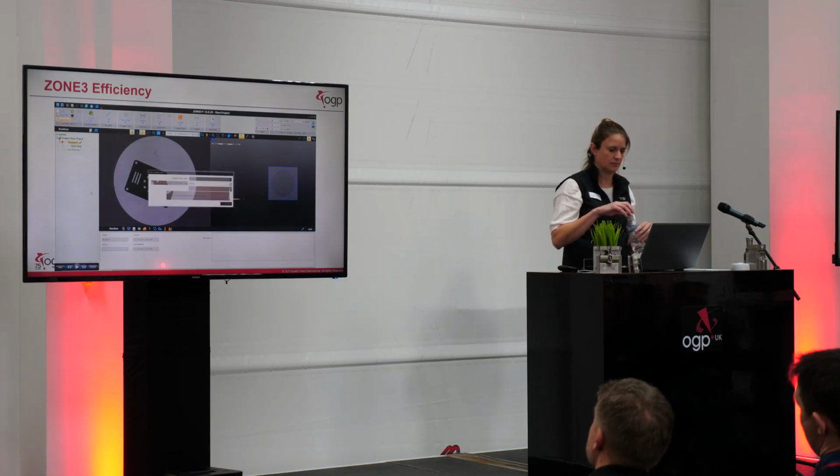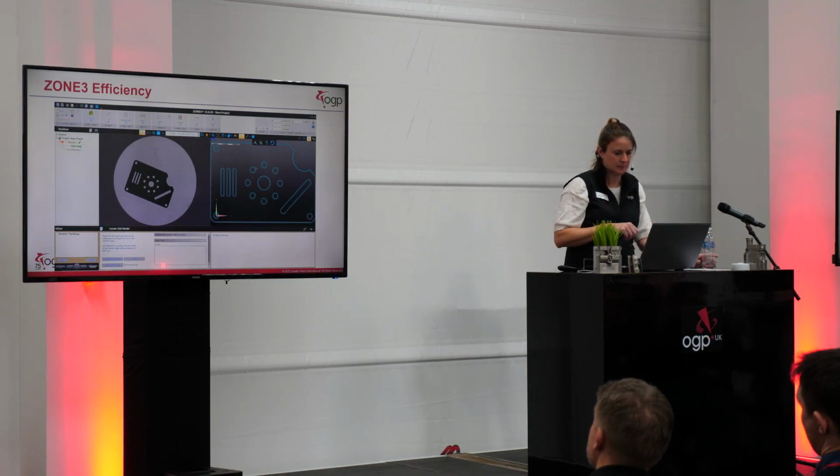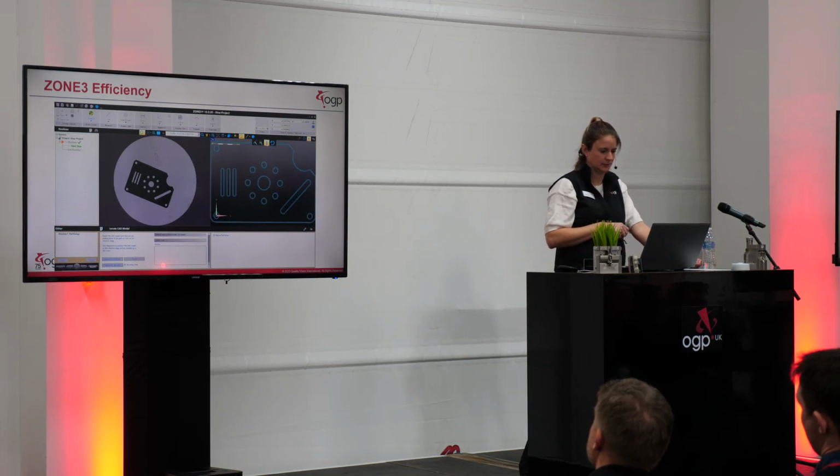When importing a DXF model of this part, the material direction is automatically determined and shown by crosshatchings in the model window. These can optionally be flipped for the whole model or individual entities. To automatically align the part to the CAD model without any programming or manual setup, the patented Reposition via Video tool will compare a trace of the actual part to the CAD model and automatically align it.